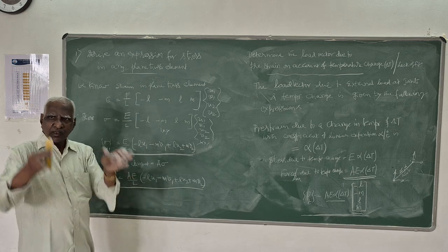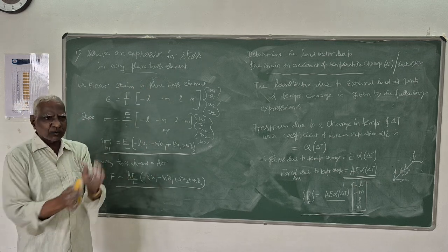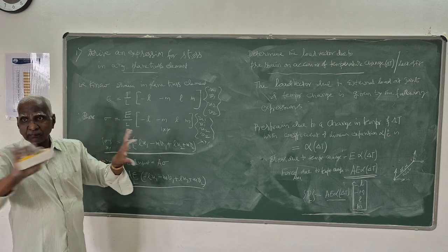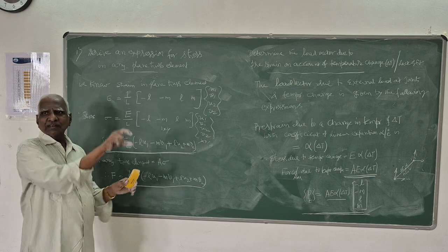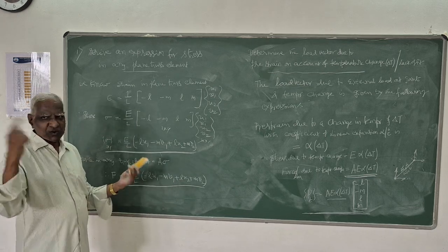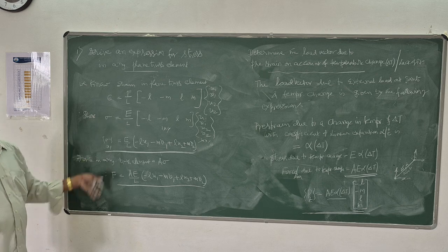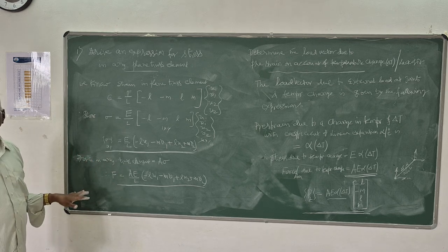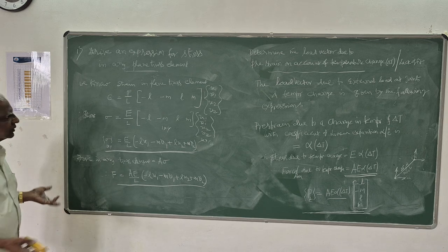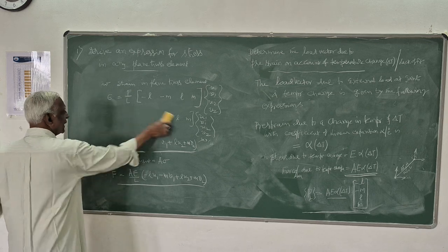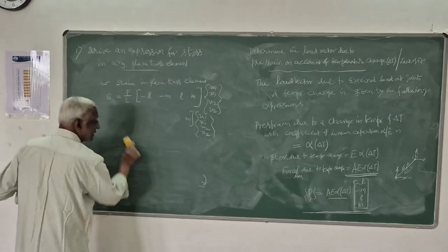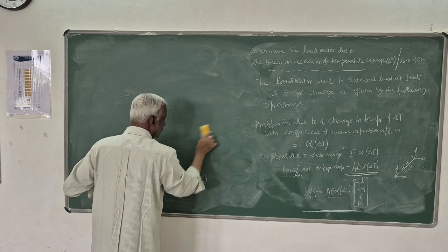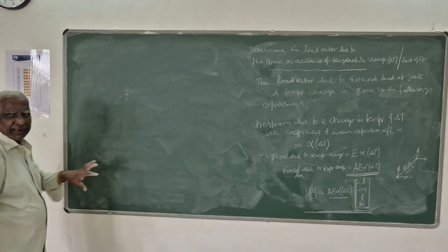Stiffness matrix is known. Right hand side, the load vector, is known. The only unknown is Q. Kq is equal to P. That's the element equation, with Q being the displacement. Then once you know the displacement, stresses and forces you can find. This is the complete analysis of any problem. Now we will take up one simple example and close this truss analysis. This much information you should know before analyzing any truss.